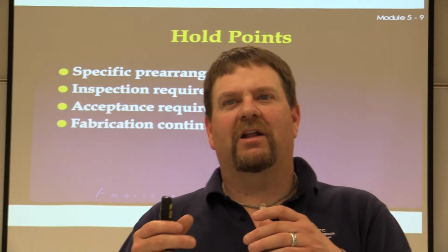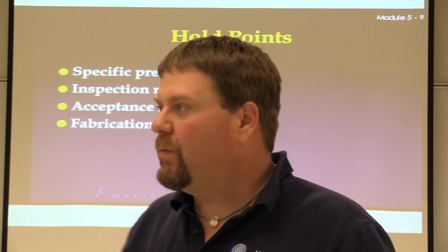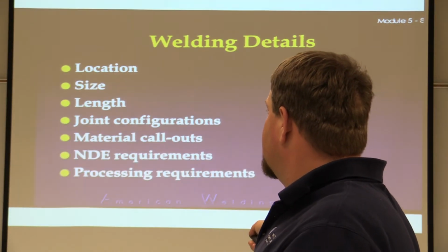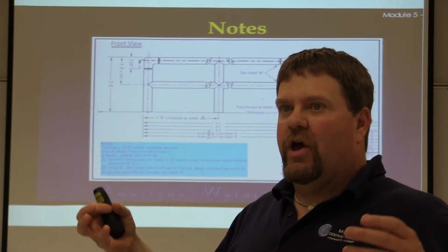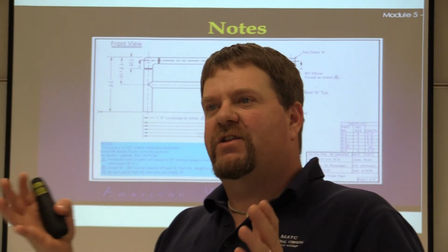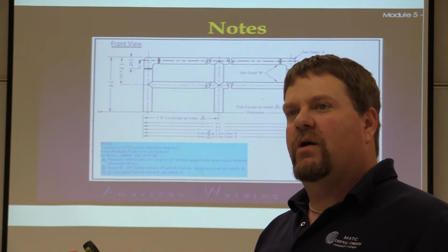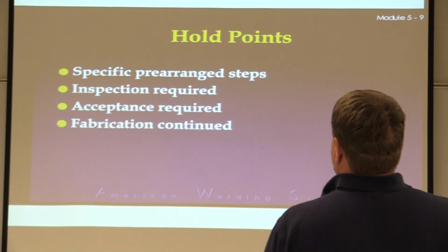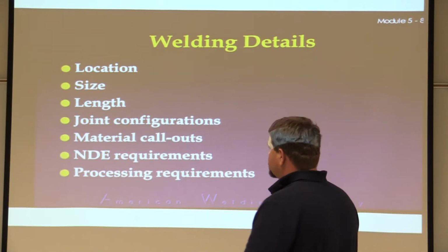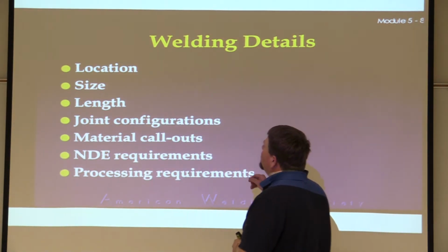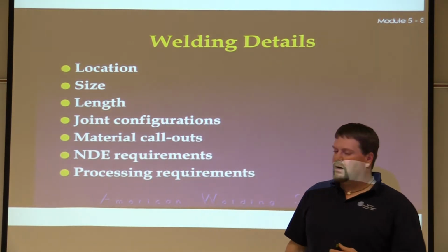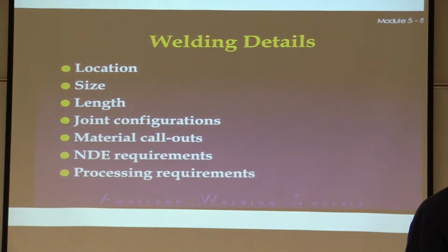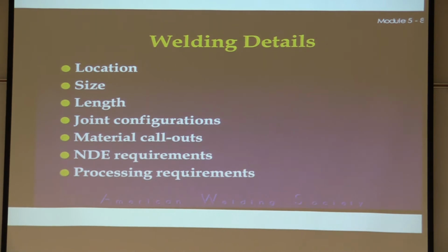By the time it cools back down and it gets up to put in on the fitted piece, say it's in this section right here, and it's cooled down at that point, all of a sudden it's going to be too small because you cut it while it was hot and ground, okay? So, a few of those things, the size, the length, the preheat, the cutting, those are all things to be taken into consideration before the start of any process whatsoever.